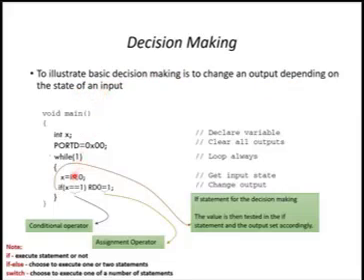Okay. So we look at program looping. Program looping executes continuously until the processor is turned off or reset. Whenever you call the continuous looping, it will continuously execute. Looking at the example, in order to enable continuous looping, you need to put while, open bracket, value 1 or true, then closing bracket, and then an open curly bracket followed by a closing curly bracket. Anything written between the open and closing will be executed provided that the condition is true.